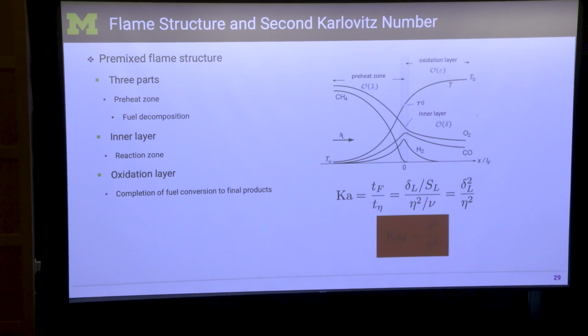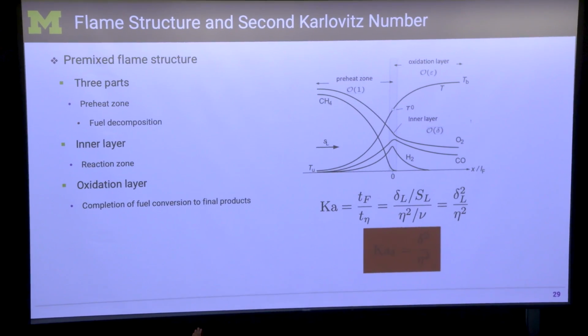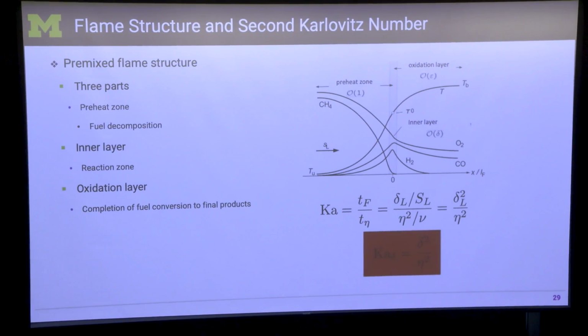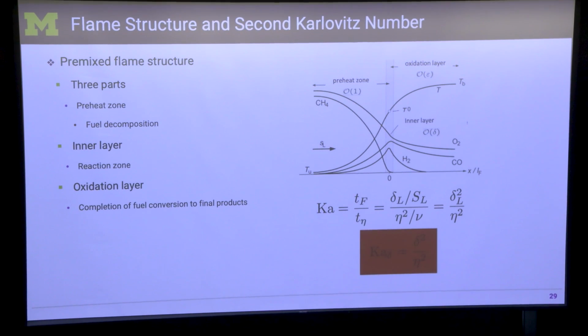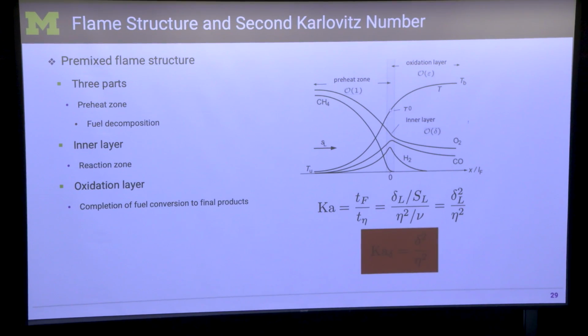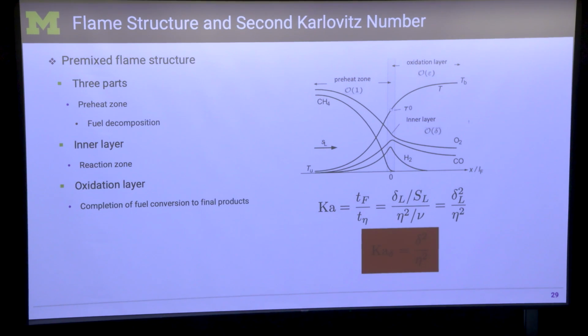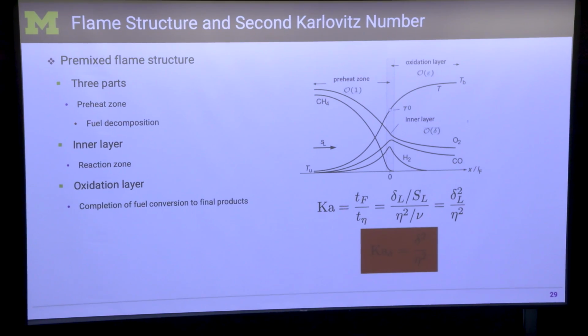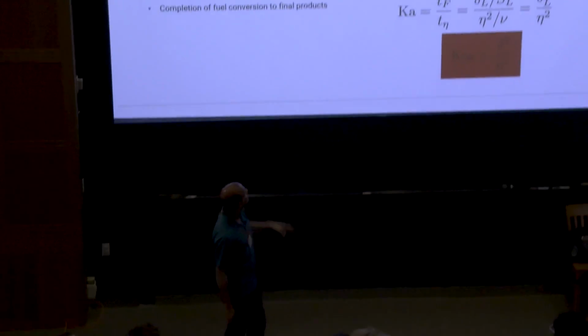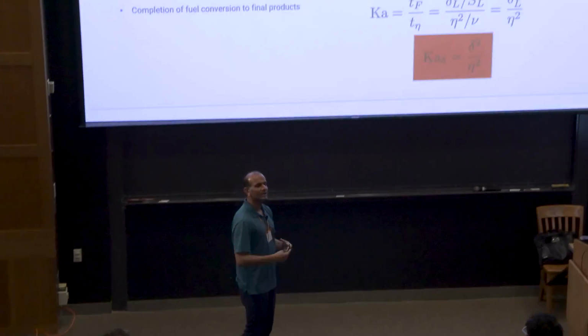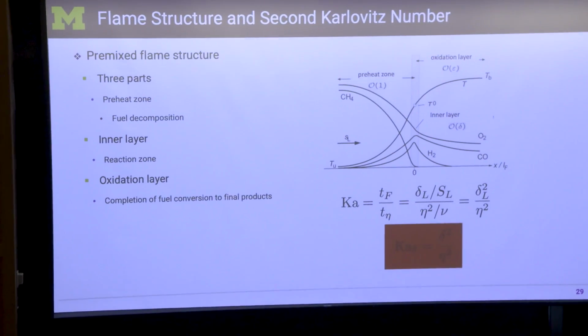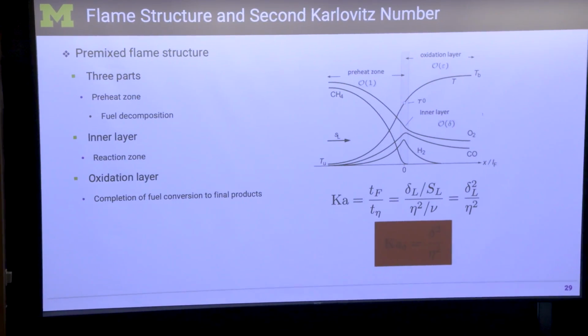And what you typically notice is that in a laminar flame, the temperature on the unburned side, so the unburned side is on the left, everything is burnt and goes towards the right. Yeah? So on the unburned side, the temperature starts going up even before you hit the flame, and that's because there is thermal diffusion. So that's what brings the temperature up. So as the temperature keeps going up, it prepares the fuel-air mixture to burn when it reaches that flame front.